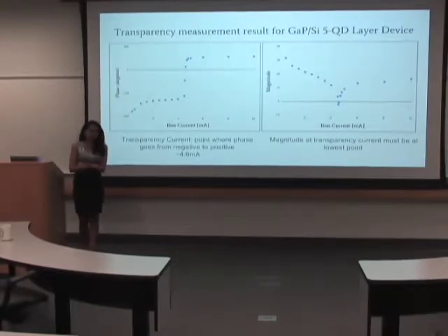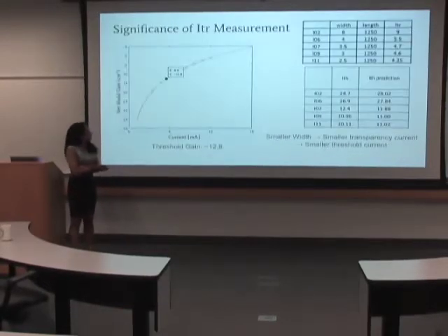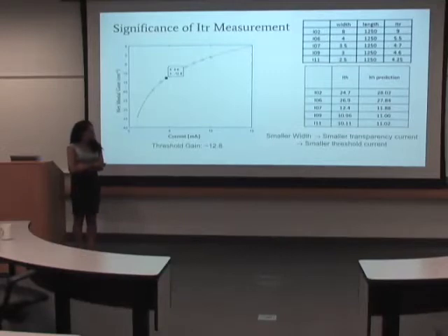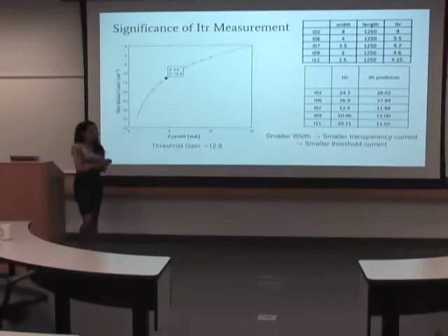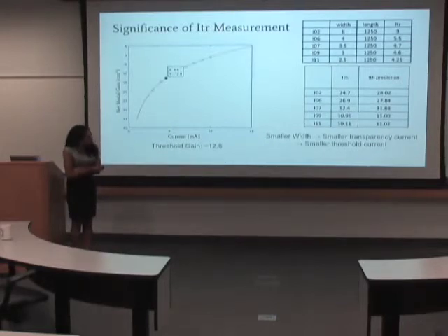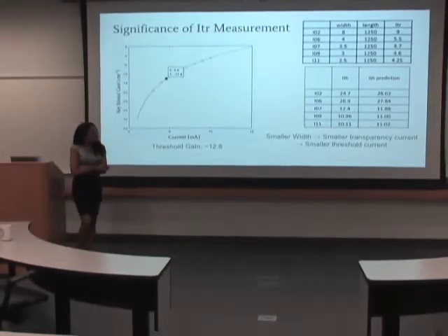The basic structure that we used was that the laser and function generator would go into an amplitude modulator, which would create an optical signal going into the fiber optic cable and going into the device. And the electric probes basically, with the DC bias, put current across the NNP junctions, and we were able to calculate the magnitude and phase of the RF signal detected from the probe pad using the lock-in amplifier.